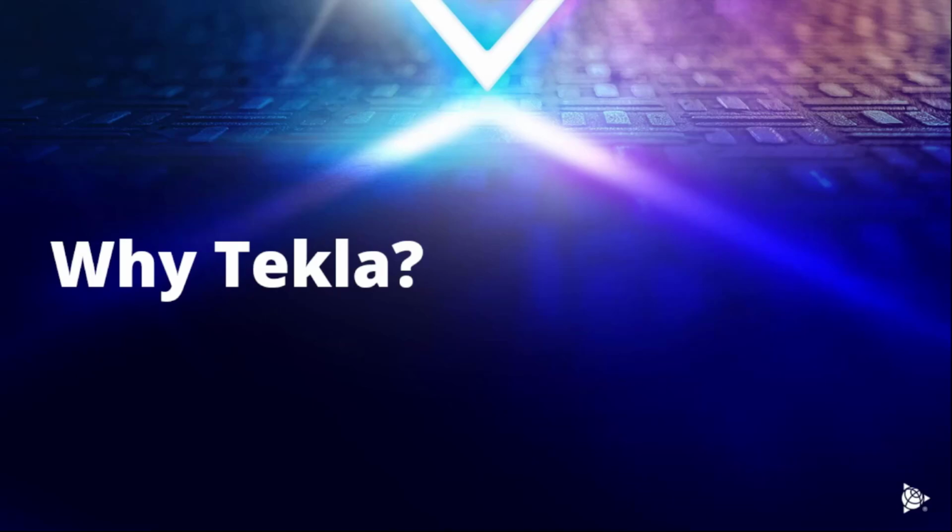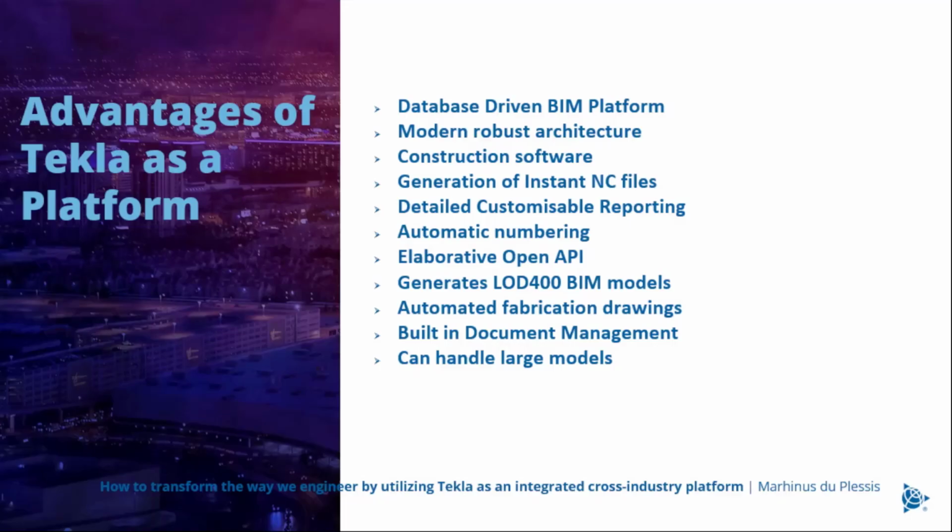So why Tekla, in our opinion? Tekla is one of the better database-driven BIM packages or platforms. What this really means is that there are no sketches that drive anything inside the model. We have coordinates, and we just apply specific attributes to those coordinates. It's got a modern and robust architecture. Tekla wasn't built off a 2D platform where they tried to convert it into 3D. Tekla was built from the ground up, and in my opinion, it is one of the stronger 3D platforms existing at the moment.